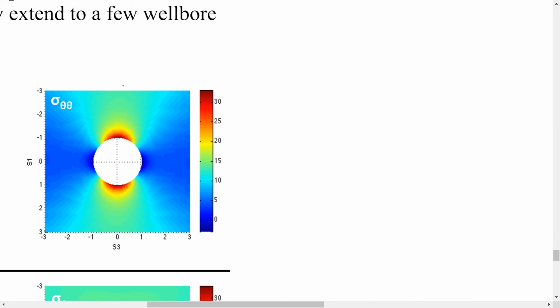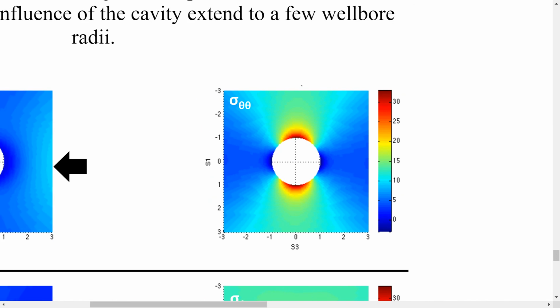So if the maximum horizontal stress was pointing in the vertical, then theta equals 0, which is at the vertical axis, correct. And your wellbore would always fail in the opposite direction, right? The shear will always be located opposite to the direction of the maximum stress. And what about the compression? These points are always opposite to the direction of the maximum stress. That is shear, not the compression. This is failure in shear.